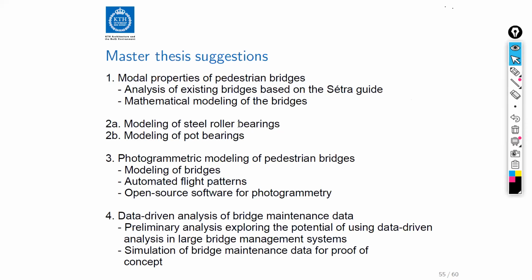But that was the main issue when I presented my PhD thesis, that is, how can we get bridge owners to accept more advanced analysis techniques and so on. If we can show that we get twice as much damping from an existing bridge, and if that leads to the situation where we can keep the bridge without doing any vibration mitigation things that would in turn lead to new maintenance needs and so on, that leads to a lot of savings in society. So this topic is really important for railway bridges, I would say.